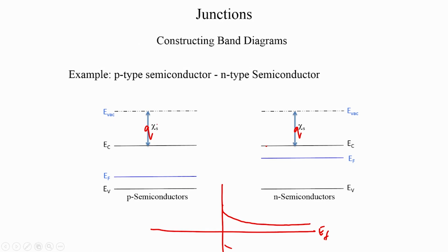And in the p-type material, the material has now received electrons. It had a small number of electrons initially, but now it has received a lot of electrons from the n-type material. These electrons have all diffused in from the n-type material, and therefore this region near the junction has got excess electrons, and the conduction band would like to move closer to the Fermi level in order to reduce the EC minus EF gap. Therefore, the p-type material will see a band bending where the conduction band bends downward to meet the Fermi level.